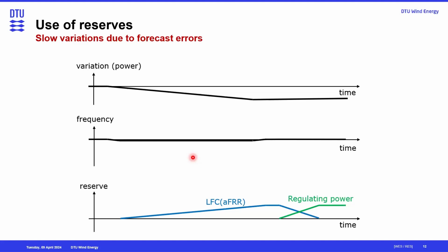Because if you are operating with 80% renewable penetration, and if all of your frequency restoration reserves is being used by the forecast error of the renewables, then the contingency happens. Then you are in a major risk because you don't have that reserve available anymore to help you during the fault, right? And then we'll go into blackouts and whatnot. So we want to prevent that.